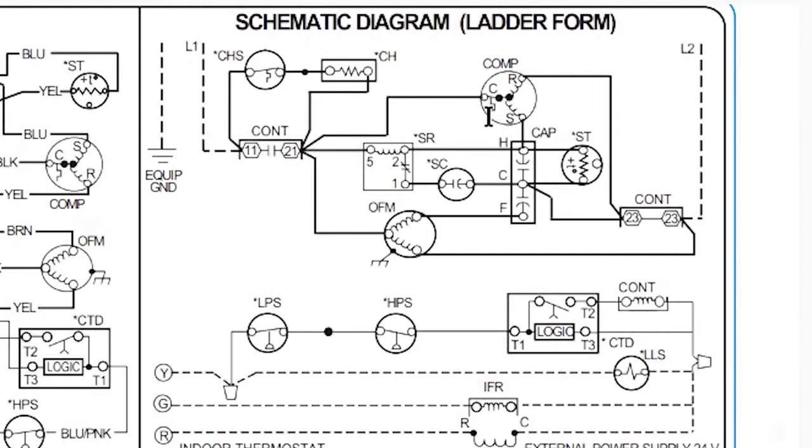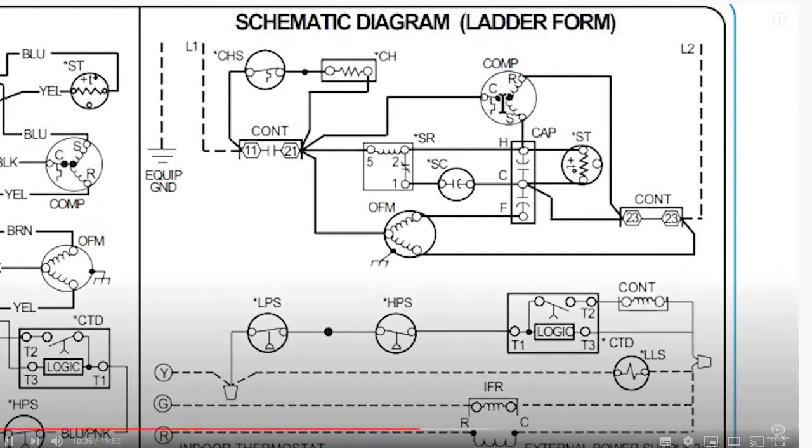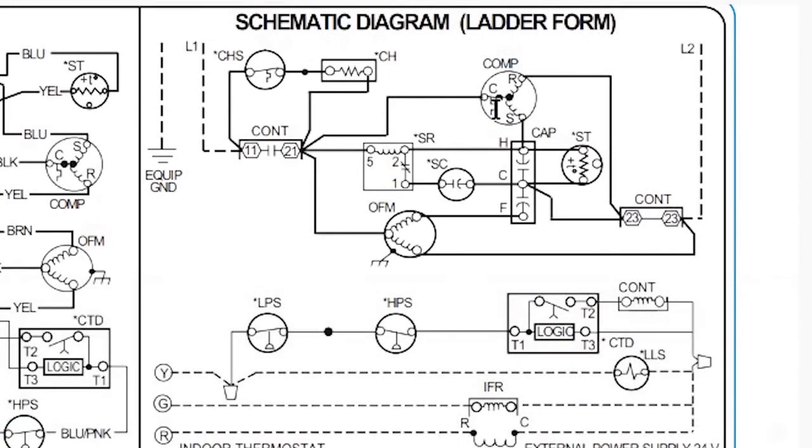You'll notice inside this compressor, there is a normally closed open on rise thermal switch. Again, you read it like a book. It's kind of hard to see because this is really, really small, but if the temperature were to rise, this switch would open, very much like this one here. You see it's the same sort of symbol. And so that's what a thermal overload is. It's a switch that breaks common. Common is not a winding. Common is just a point in between the windings of run and start, but it's got a thermal overload in there, and that's where you connect L1 in this case. So that shows you how that thermal overload is wired into the circuit.